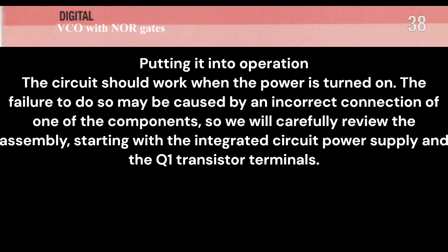Putting it into operation. The circuit should work when the power is turned on. Failure to do so may be caused by an incorrect connection of one of the components, so we will carefully review the assembly, starting with the integrated circuit power supply and the Q1 transistor terminals.